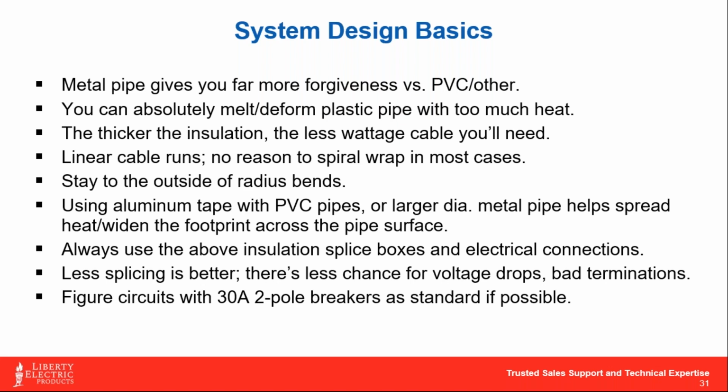That's just basic logic, right? Many times the installation can get expensive, so sometimes we see a balancing act between what cable versus how much insulation. But know this, once you start getting up into 1.5 inch, 2 inch insulation on that pipe, you're not losing a whole lot of heat. So it definitely helps the efficiency and being able to lower the output of the cable.